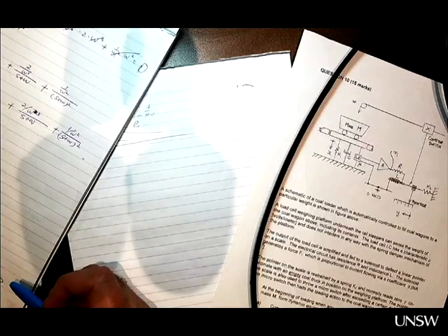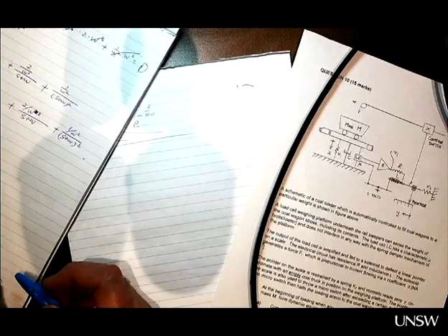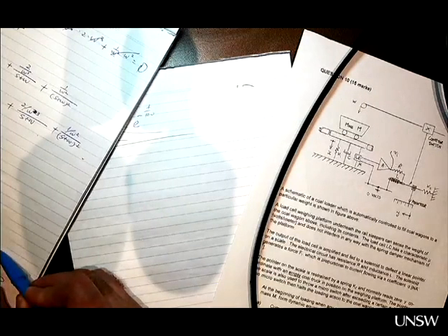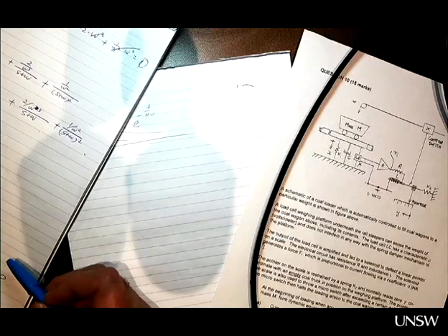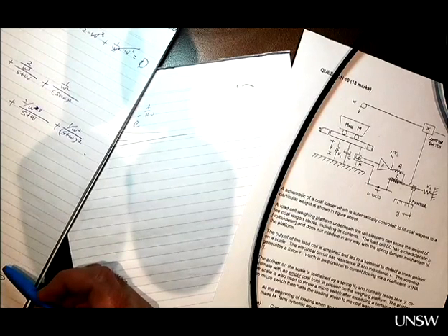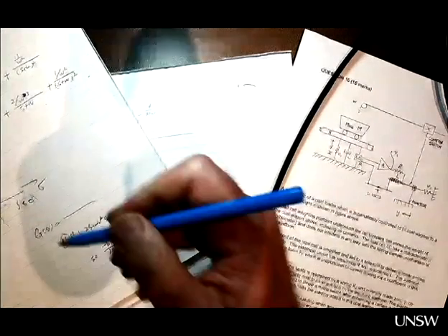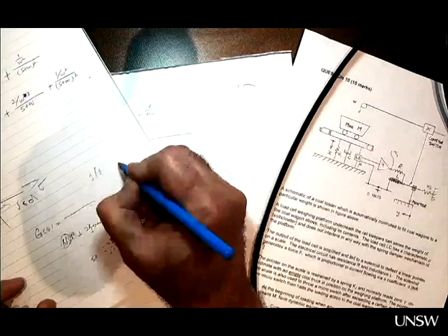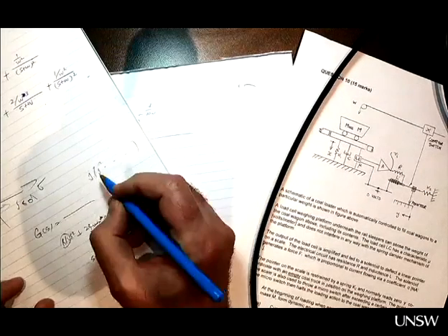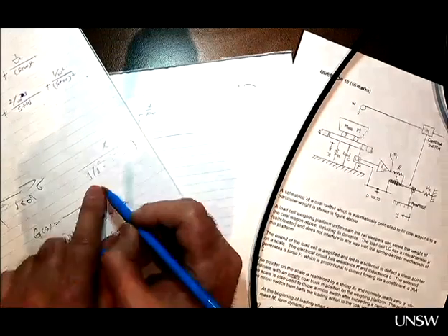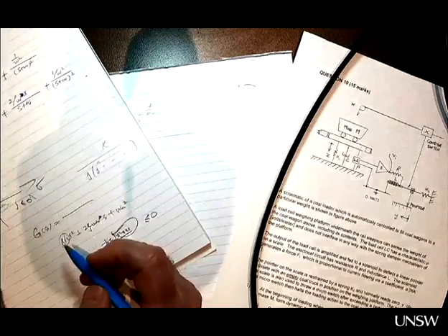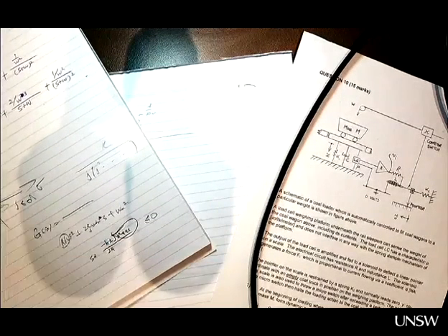So actually, this is not your omega n squared. Omega n squared will be this divided by this. But this doesn't give a root here. What I thought you were asking is that if you have s and then some constant, s plus k, is this system stable or not? It is neutrally stable. So do we consider that as stable or unstable? It's not either, it's just called neutrally stable. So we still need to conclude that case.